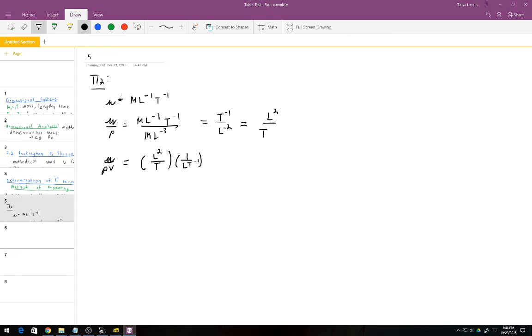And so this one then is just going to give me L. And then finally, I can get rid of that L by just dividing by our diameter D. So mu over rho d V equals L over L, which is just 1. Dimensions, dimensions, dimensions. So I see now that pi 2 is equal to mu over rho d V.